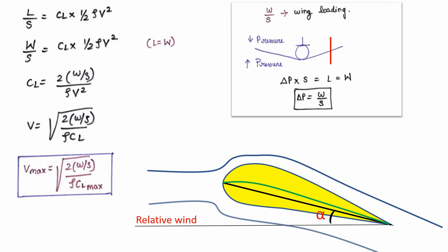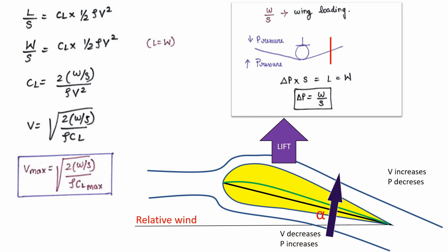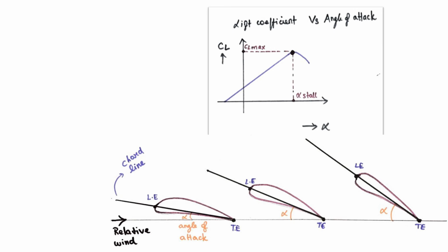As air flows over the wing, there is low pressure region formed due to the increase in velocity on the upper surface of the wing, and high pressure region is formed due to decreased velocity on the lower surface of the wing. This high pressure created at the bottom moves to the top surface of the wing, thereby pushing the aircraft upwards, resulting with the lift force. This works based on the Bernoulli's principle in lifting the aircraft from the ground surface.